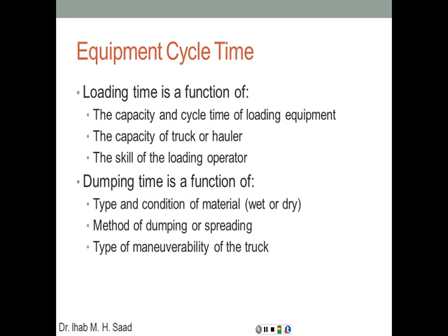The loading time is a function of the capacity and cycle time of the loading equipment, the capacity of the truck or hauler, and the skill of the loading operator. If you remember what we discussed before about excellent, above average, average, below average job conditions, it had something to do with the angle of swing, for example, of the equipment.